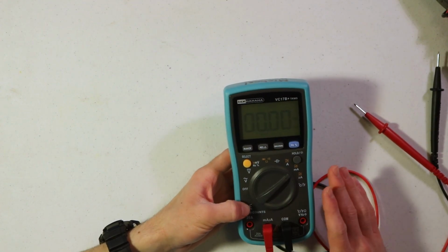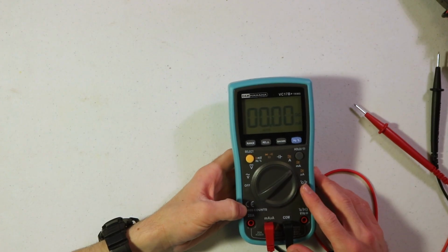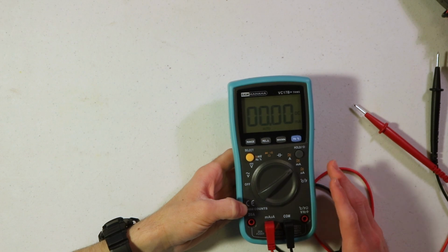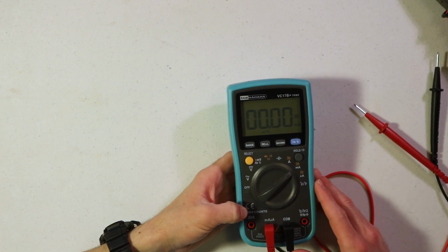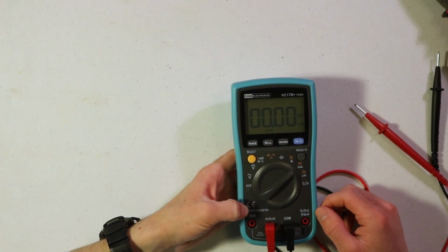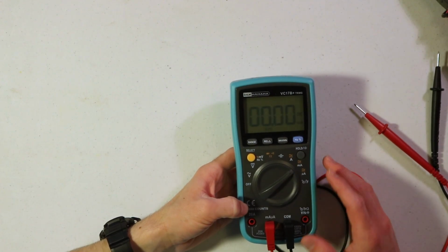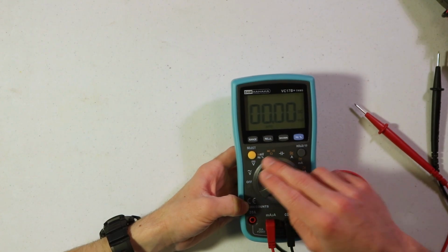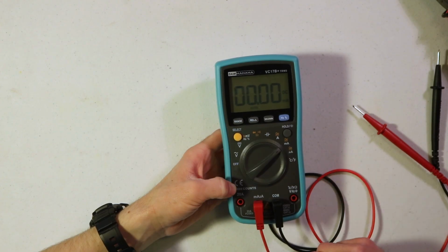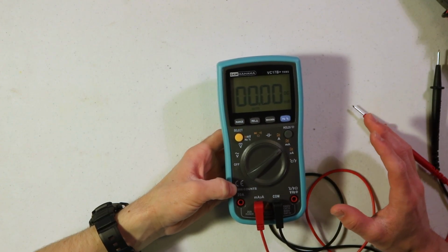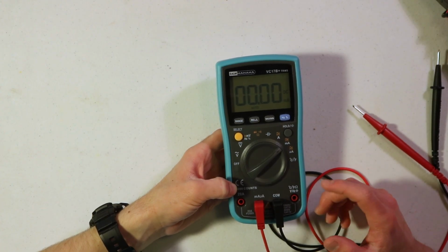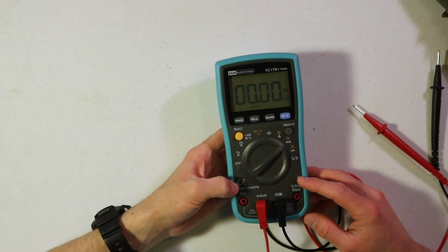So something that is very important when you're measuring current with a multimeter is always connect it in series. So we talked about the difference between series and parallel circuits. So series, again, just put it in sequence with the things that you want to measure the current flowing through. And if you don't do that, if you connect it in parallel, it's going to act like a short circuit that will connect between those two points. All the current is going to flow through there. It'll be a large amount of current with very little resistance, and you'll burn out the fuses on your multimeter or even destroy it, and it will stop working.